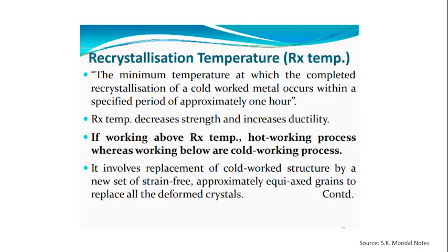Then the recrystallization temperature, because there will be two types of forming, mostly hot working and cold working. Hot working will be above recrystallization temperature and cold working will be below. It is the minimum temperature at which complete recrystallization of a cold worked material occurs within approximately 1 hour.